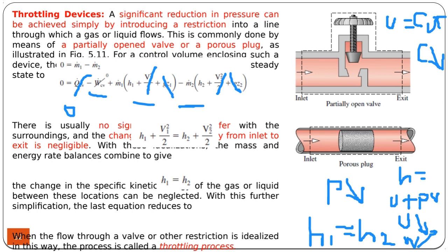In a refrigeration system, we will see the refrigeration system later, as the liquid in high pressure is throttled or is expanded through a throttling device, its pressure goes down drastically while it expands, and also the temperature becomes much smaller with respect to the inlet.